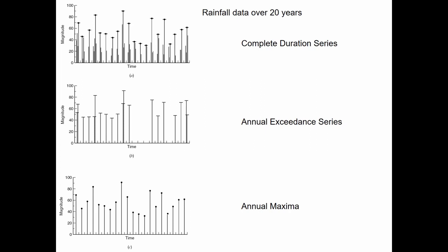And in risk, we have to consider the fact that you can't have more than a single large event in the same year. So generally, the recommendation is to use annual exceedance series, rainfall, and flow data because it's more representative. The problem, though, is that some stream gauges really aren't sophisticated, like the older data before it was common to have electronic data logging. It was a float that, once a year maybe they'd go to a stream and they'd see how high the float got, and the highest water would cause the float to stay at a certain part on a gauging pole. And so the water would rise and it would fall down. Certain stream gauges would only be visited once a year, and they'd be looking at what was the maximum flow in that entire period before then. Or maybe the gauge is only visited on a monthly basis back then, before the electronic communications was well developed and data logging wasn't common.